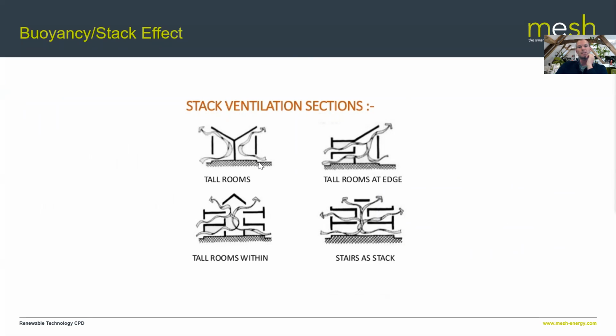You know, maybe in a domestic vaulted ceiling application, again, you draw in air at low level and you exhaust that air at higher level, and then you've kind of got bits in between as well, using staircases as your chimney. There's all kinds of different design iterations, and no doubt you guys will have seen this. And these principles are simple. There's nothing complicated about them.